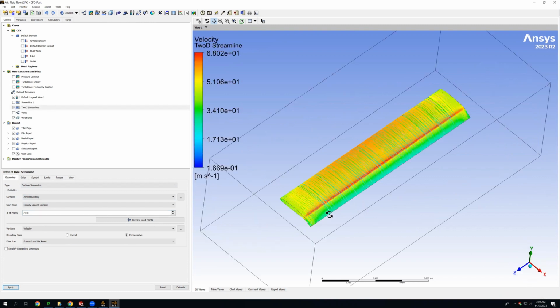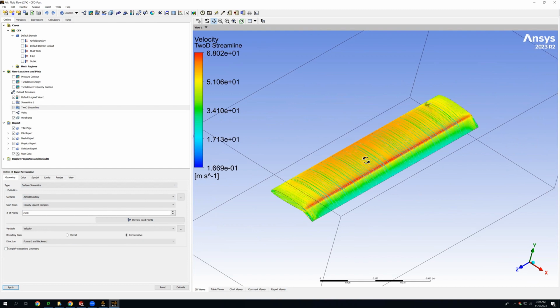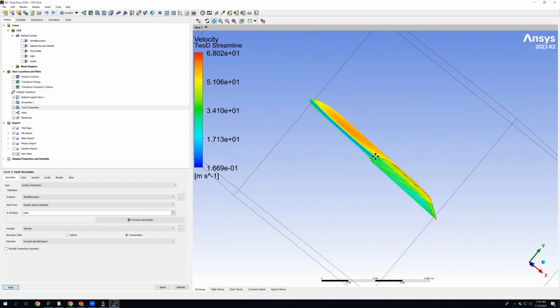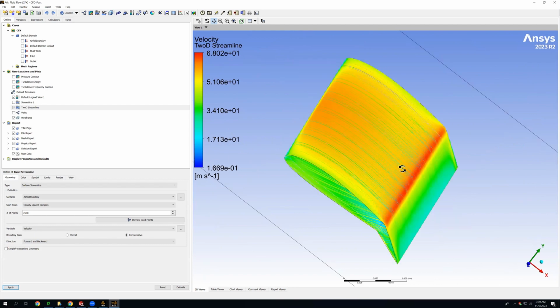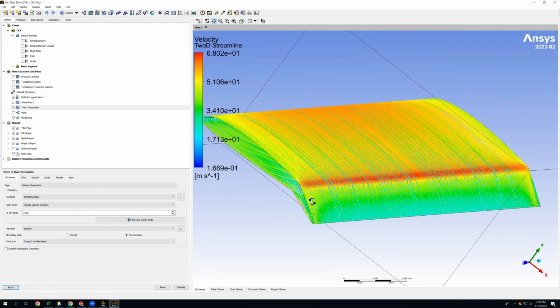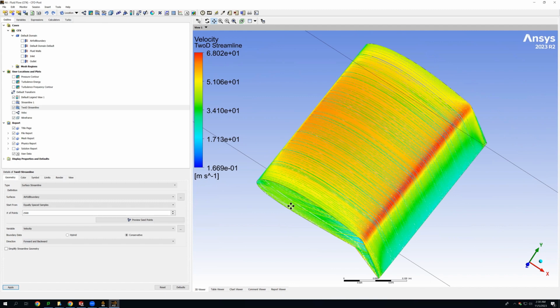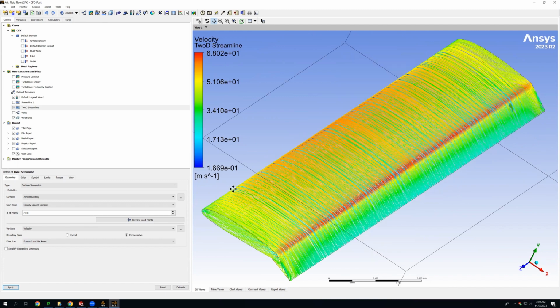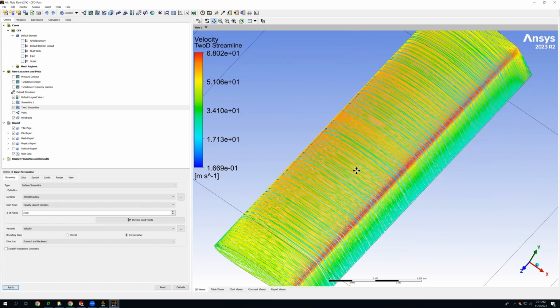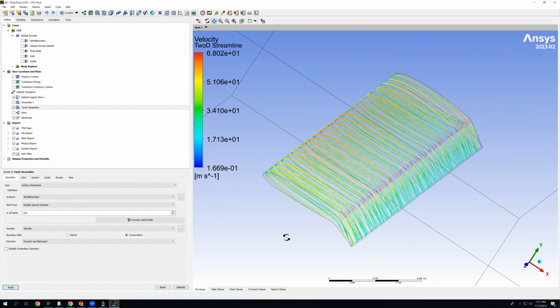Yes, and here we can see a very detailed image of how the velocity profile changes on the wing with a very slow position at the front, an increase on the top, and a massive increase at the flaps. And its opposite is basically reflected on the underside. You can also see how as it approaches the tips, the velocity changes less extreme. From blue to orange, it's only blue to yellow. This is due to the previously mentioned effect of the air curving onto the bottom, and so that decreases the lift generation by decreasing the velocity change. Yes, and if we lower the resolution, you can see the individual streamlines and how they behave.